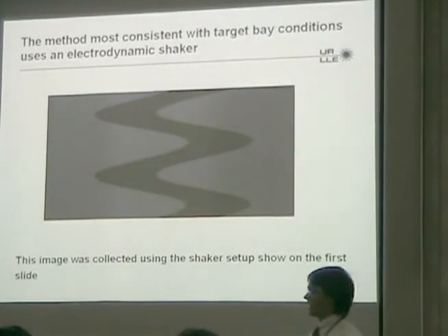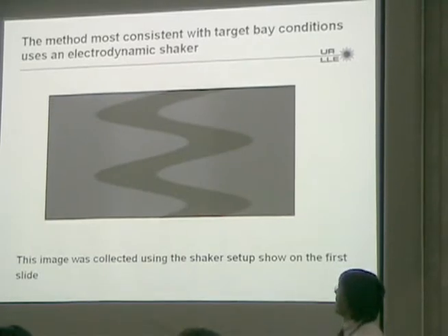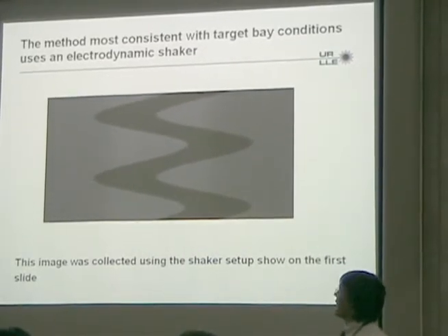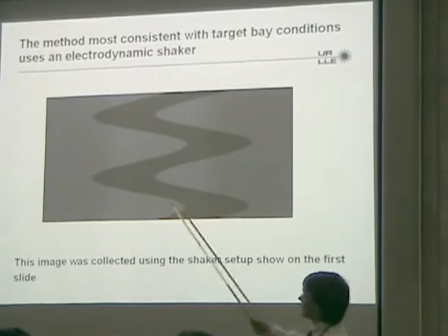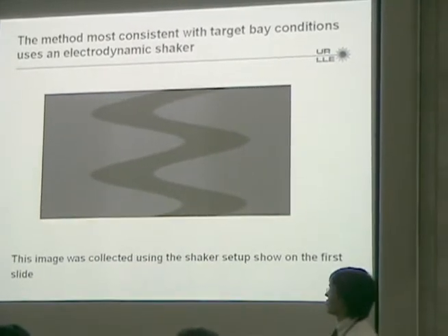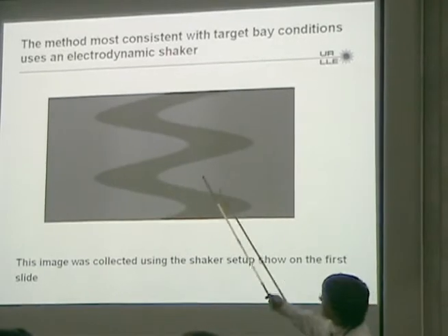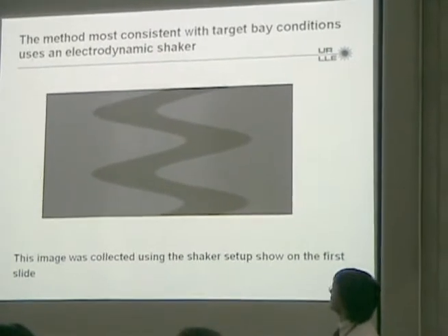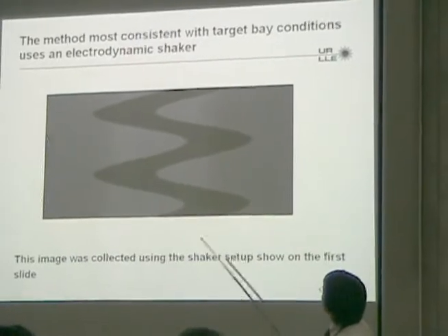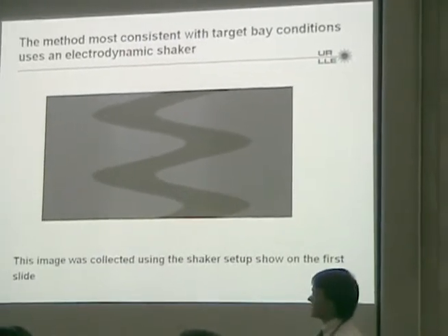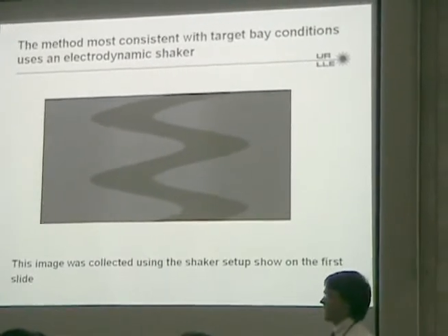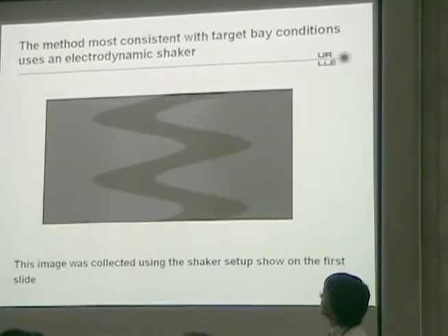So the third setup I used was that electrodynamic shaker I showed you at the beginning, and I had some target that I was viewing with the camera that was being illuminated by an LED, and it is a much larger target because it was magnified to a much larger resolution, so that each pixel on this target represents 3.83, or approximately 4 microns of actual space. And this image is much more reliable because it is continuous, it's very evident where the target is, and it has a significant magnification, so it's easy to see where everything is.